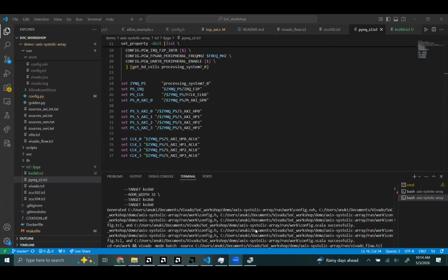Okay, thank you so much for the demo. There's a question. It's asking if I'm using a Virtex UltraScale, can I use the same Zynq processing system? I think Virtex UltraScale is just the FPGA part, just the PL fabric. It doesn't have a PS, so you won't be able to use that. Yeah, that's the only question. You can take off. Right, thank you so much.